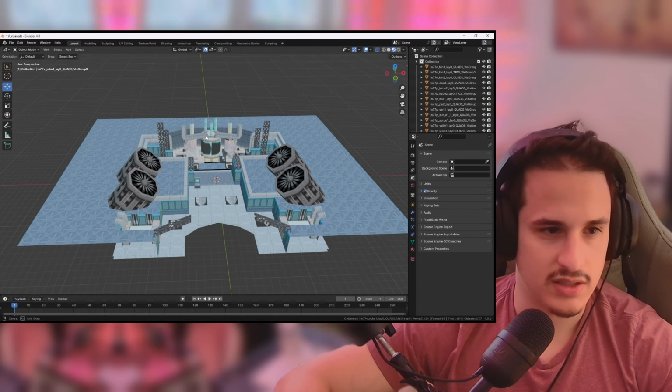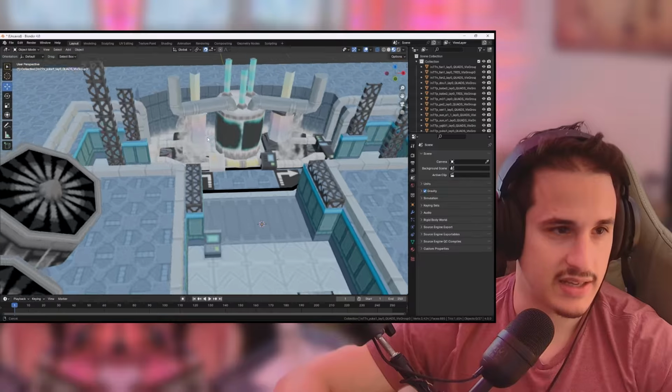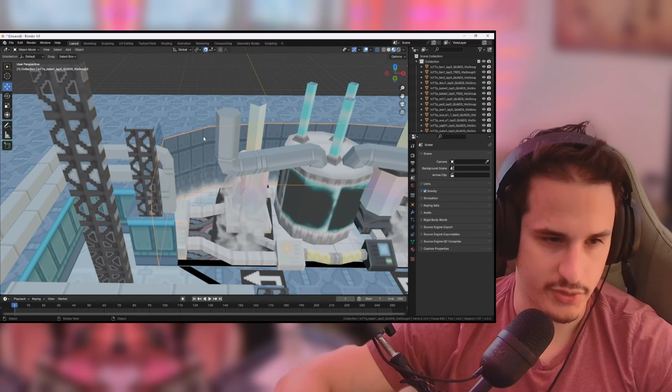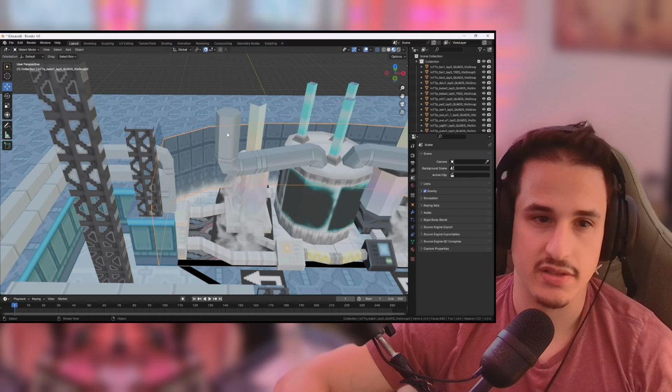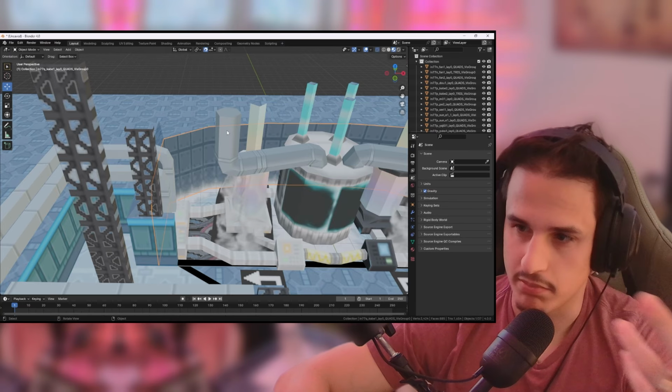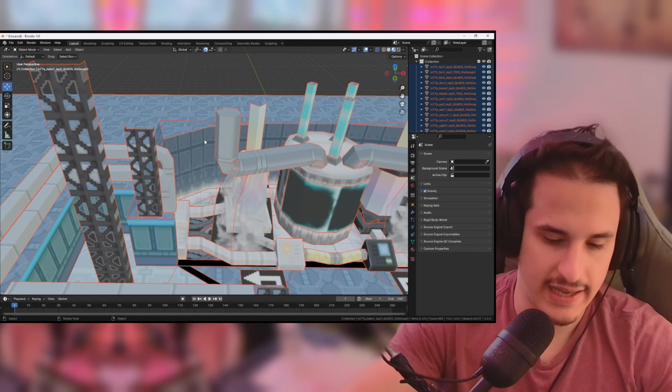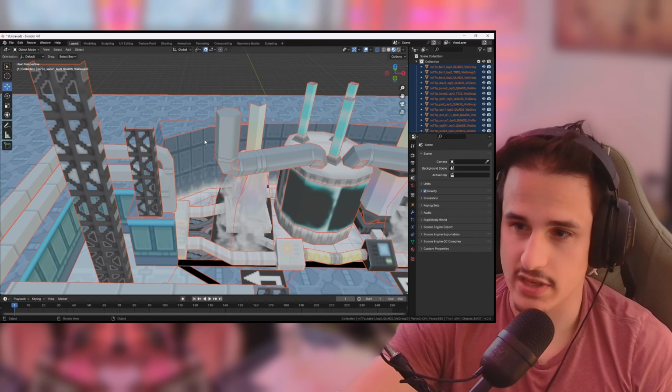And the interesting part here is that it is a curved surface, so we're going to actually need to create a new model by itself. So we're going to select the wall and then hit Control I, so we can select the inverse and then delete.